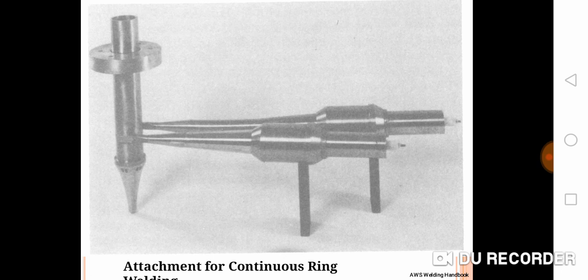There you can see the sonotrode tip will rotate on a surface, about the support of the transducers. You can see it here. This is another mechanism for continuous seam welding. In all these cases, the sonotrode mechanism will change. The shape and the movement of the sonotrode mechanism will change. Other principles will remain the same.